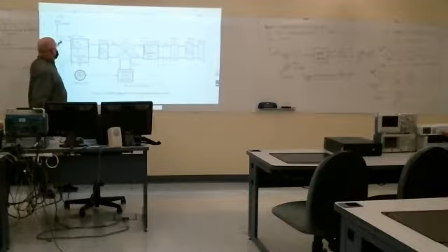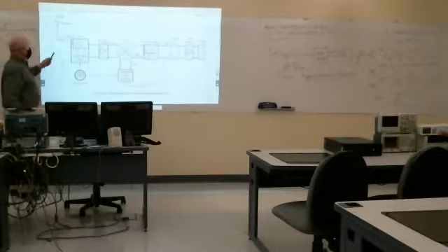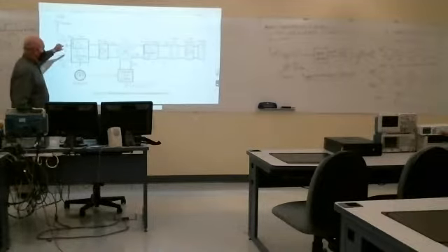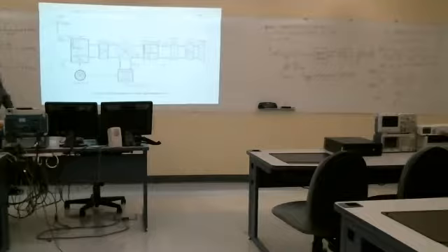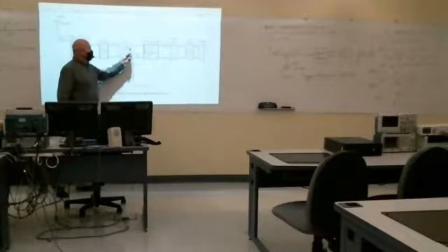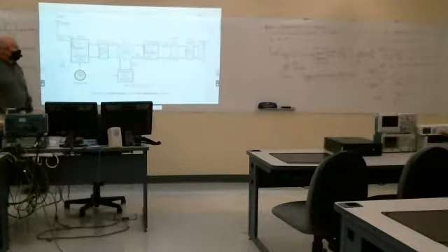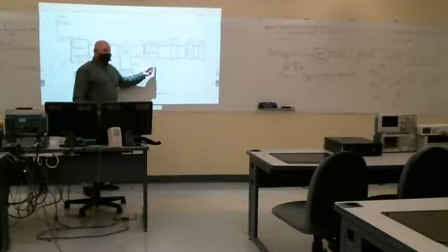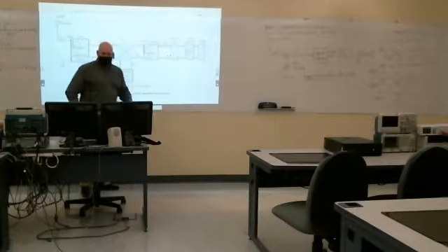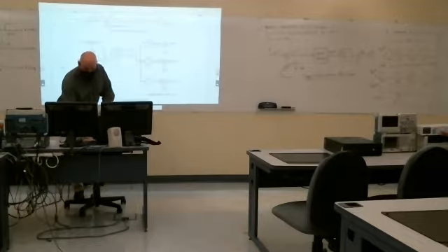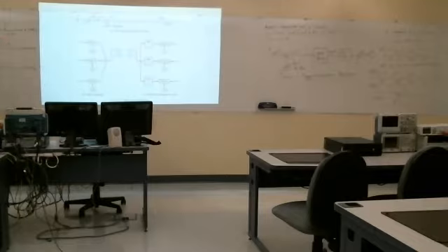But coming in off, in this case, this is a 1 megahertz, that would be 1000 kilohertz. We want to listen to a 1 megahertz, so our local oscillator would be 1455 or 1.455 megahertz, so that when we mix, that station would be translated to 455 kilohertz. And then our intermediate frequency bandpass filter would eliminate it. And then here's our demodulator for AM radio. That's an envelope detector.